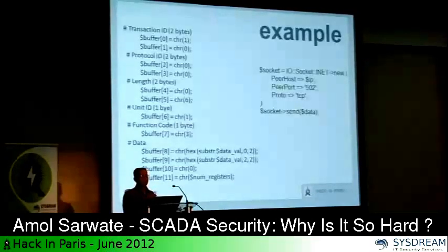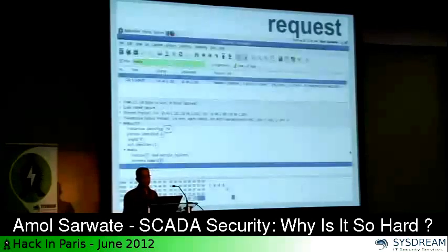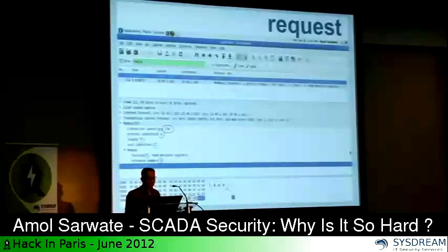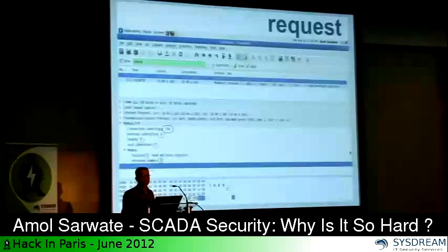And you put data, which registers you want to read, how many registers you want to read. And now this is Modbus on TCP/IP. So you send it over using simple TCP sockets, port 502, which is the default port, to the server. So the request looks something like this. You can see in circles that I think Wireshark has identified transaction ID 256, protocol ID 0, length 6, unit ID 1.